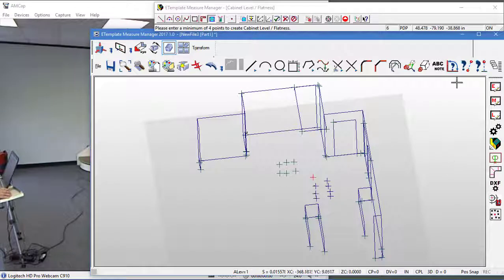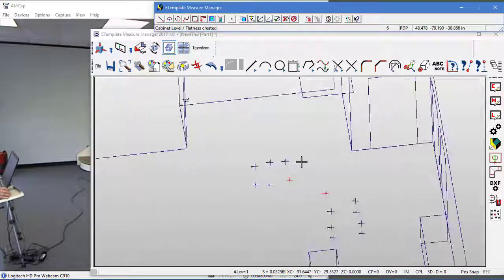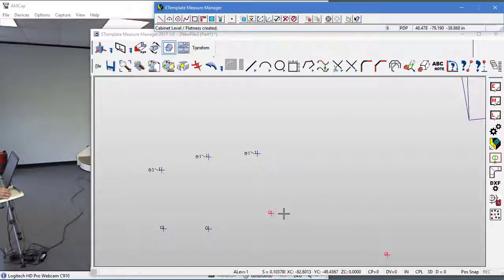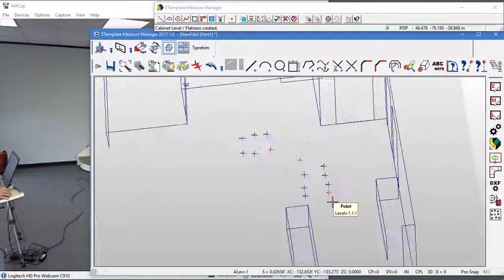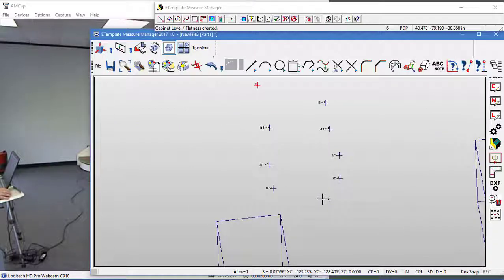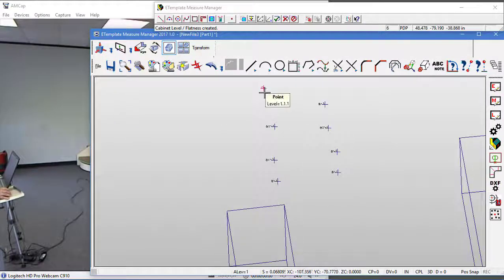Put that in focus. So now what I've got is I've got these compared to themselves. And I can see this is 0, and this is a 16th. So it's a little bit, the floor slides a little bit that way there. Let's come back out. Let's look over here. Over here we've got, again, it's not too bad a floor. It's 0 there, and an 8th and a 16th pretty much along here.